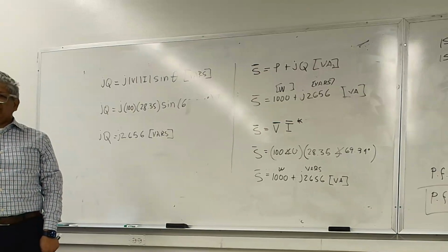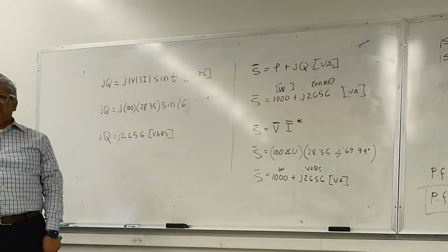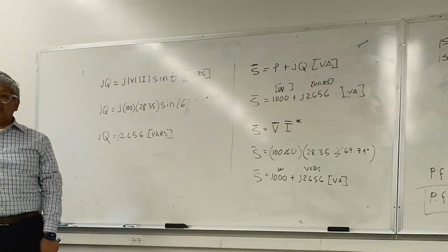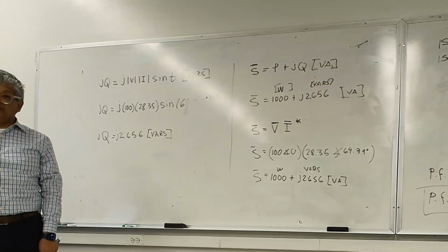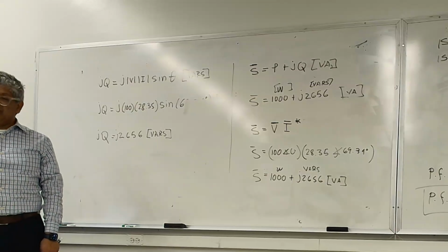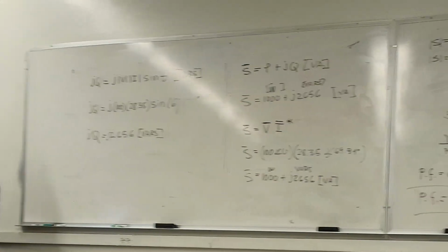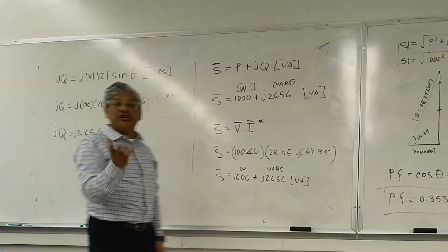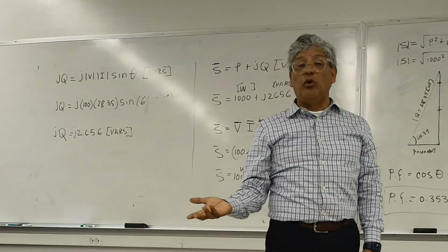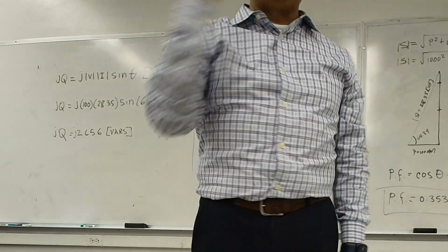As you turn on vars, the voltage will start going up. The reactors have the opposite effect. They reduce the voltage. So most loads are reactors, so they reduce the voltage. So it helps your voltage profile. And then last but not least, you can use synchronous machines. It can be a generator or a motor. And they can help you improve the power factor.